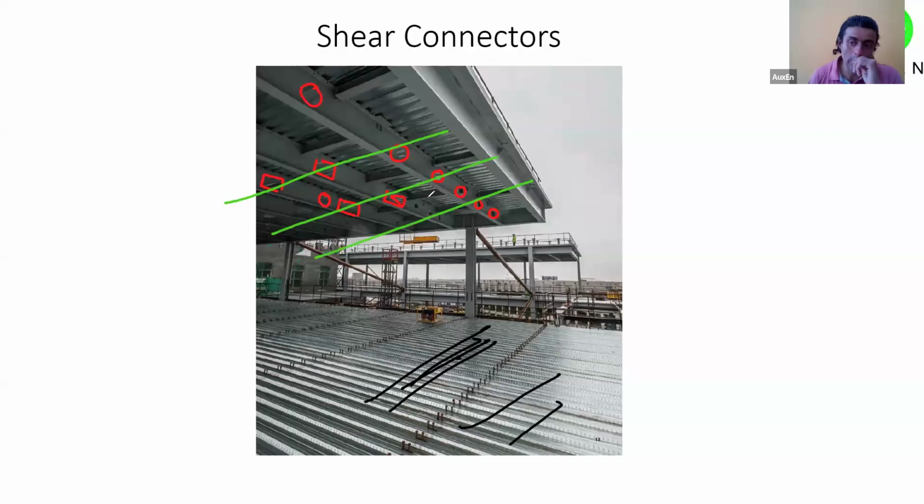So you can easily put, let's say, if at all you wanted to put a false ceiling, you can put your false ceiling right at the beam bottom flange. And for all the service lines, because you had this depth occupied by the beam, you just want to use the same depth within which you want to put your service lines. It may be your firefighting or air conditioning ducts or electrical lines or whatever. Those you can take through these sleeves that you have provided in your steel beam.